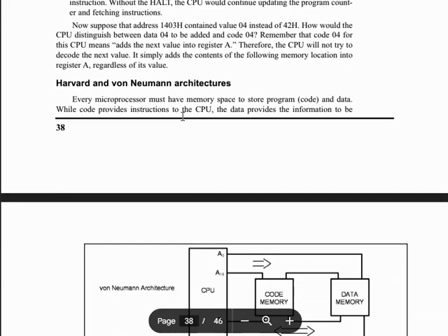Harvard architecture has separate buses for code and data, giving faster processing, as code and data access can occur simultaneously. For internal on-chip implementation, Harvard architecture is easier to implement within a microcontroller. For external implementation, Harvard architecture is more expensive in systems with external RAM and ROM, such as PCs.